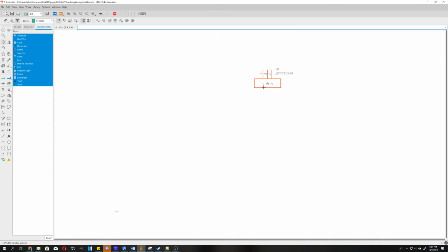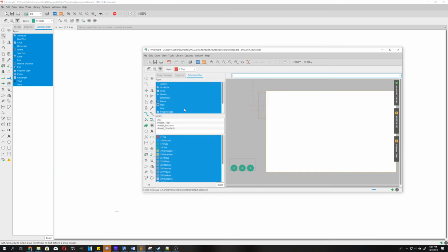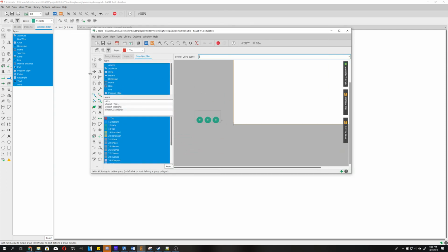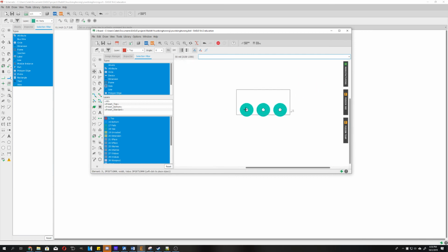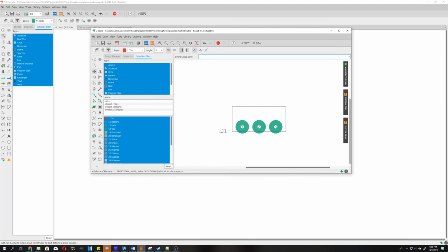So then, once you have this part in here, you wire it up, you do whatever, you can just go, generate the board, create from schematic, and there you are. We've got the item here. Click there, and place it wherever we want. Maybe reposition the label around wherever we want. Change the size of it, maybe something like that. Might make more sense. And there it is.